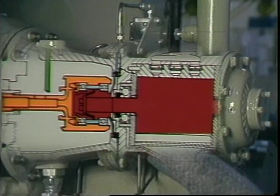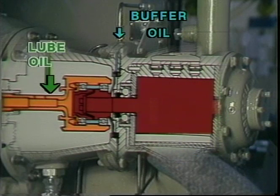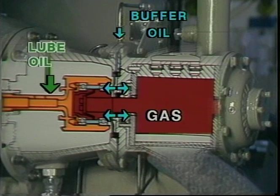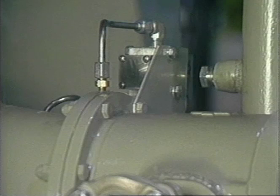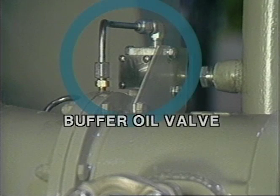Before leaving the starter motor assembly, you should be aware that lube oil is supplied through this fitting and that the clutch assembly uses buffer oil in conjunction with a gas seal to prevent starting gas from contaminating the lube oil in the accessory drive area. The buffer oil is regulated by the buffer oil valve located next to the starter motor.